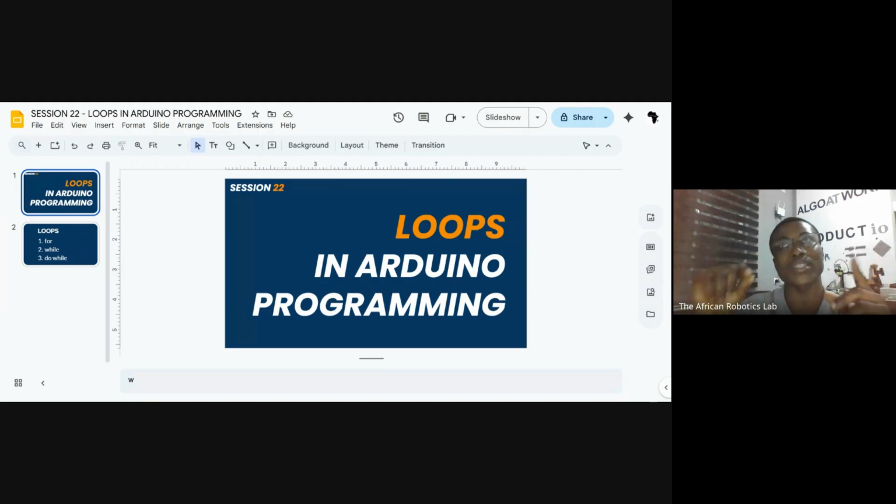And we learned that for UART, it's just two pins. We have TX, the transmit pin on a microcontroller, and the receive pin on a microcontroller. So you just have to connect the transmit to the receive, and then the receive to the transmit of the other.